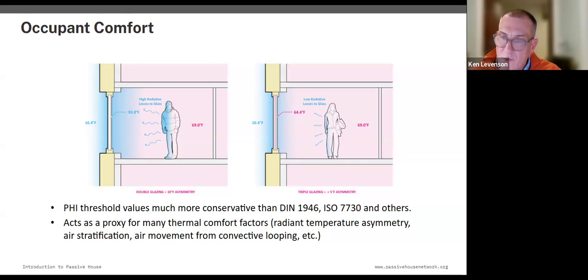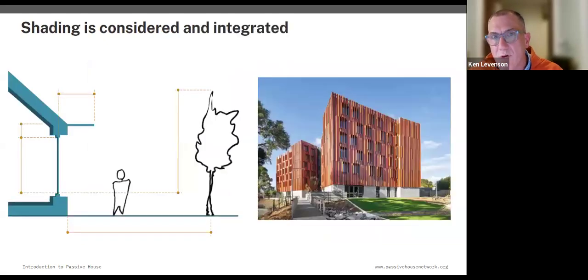The remedy for mold in colder climate zones with Passive House. So what we want to do is just make sure that the construction, the assembly, whether it's the window assembly or the wall assembly, is robust enough insulation-wise and airtightness-wise. In a Passive House, because we have control of the space, we may have indoor humidity in the wintertime of 40% or more, say 35 to 45% relative humidity.